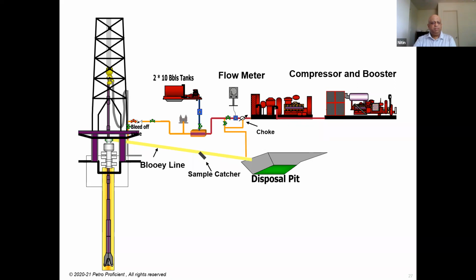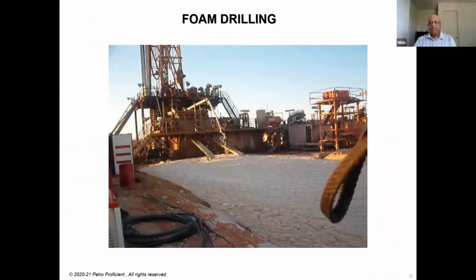And the same thing that we just discussed, but we have a chemical injection pump here, and you have a foam tank where you actually create your water and surfactant, and then you add that along with your air so that foam is created. And you inject that at your standpipe manifold or before that. So it gets into the well.